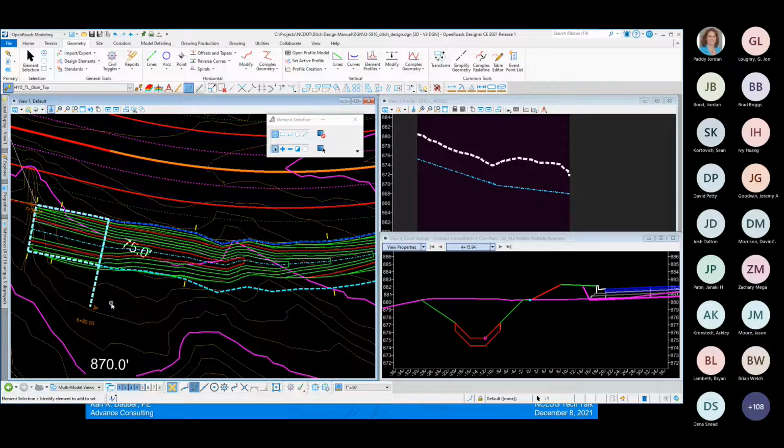Edits to the template drop do not change the templates in the library. So if you want your template changes to be reflected in your library, then go to the library first, make the changes there, then come back and use this tool, Synchronize with Library, and that will take the changes you've made in your library and then apply them to your corridor.